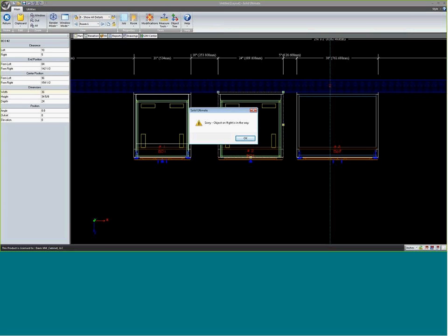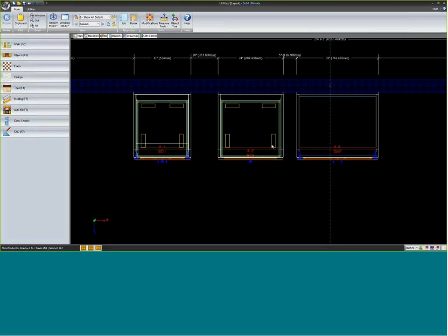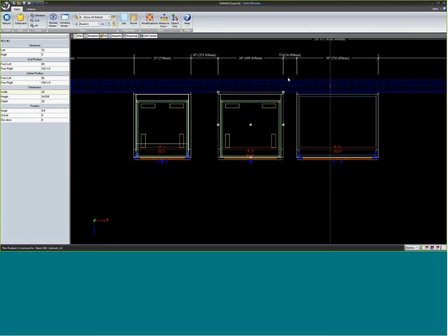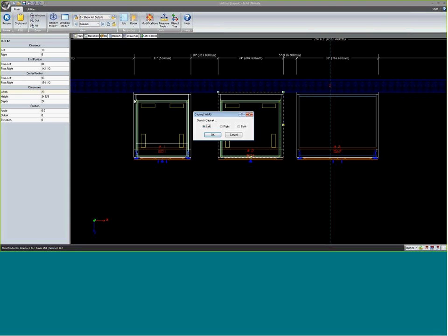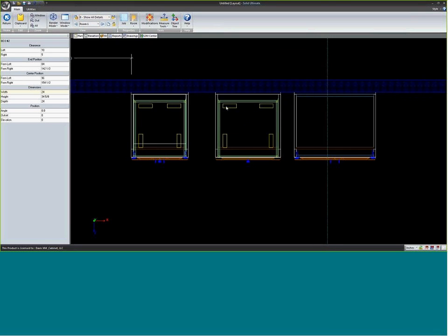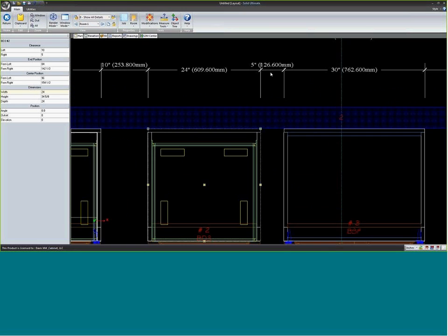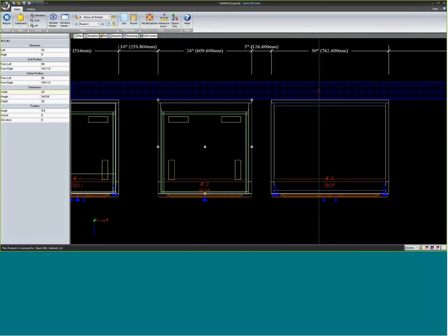It says those are two 3D objects. They can't occupy the same space. So sorry, there's something in the way. You just have to say OK and select that thing. And I only have 5 inches I could have grown that cabinet by. So I know it's 29 inches, but just to re-illustrate this, I can say plus 5 inches in there and then extend it to the right. Oh, of course, now it yells at me. That's fantastic. If you ever get a problem like that where I can fit here, but it's giving me issue that way,